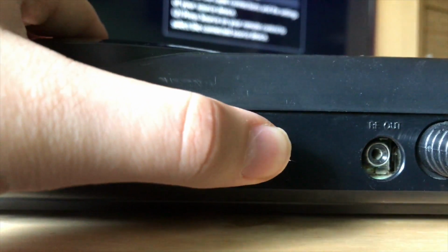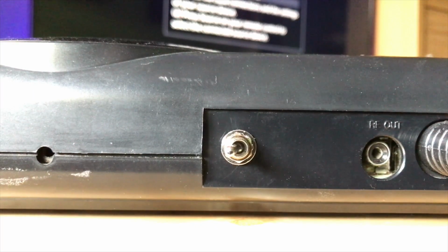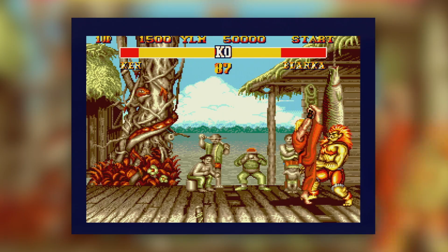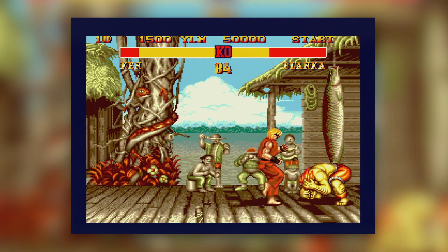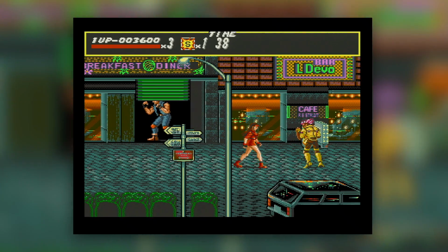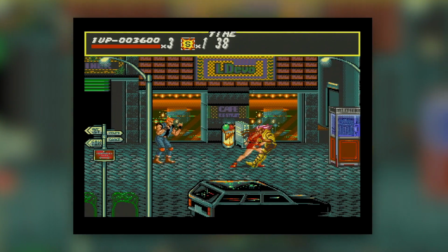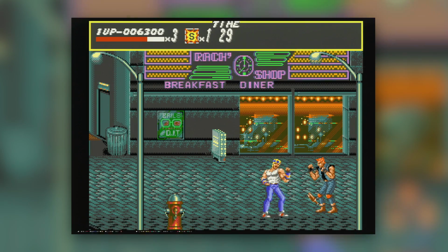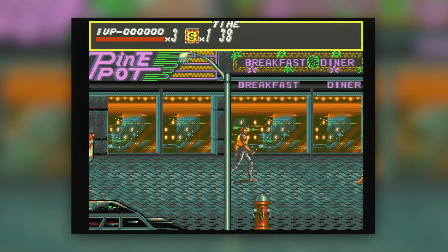However, for a quick DIY job you can mod your Mega Drive with a physical switch. The more common method is to add two switches, one to change region, the other to switch between 50Hz and 60Hz speed. But the mod I'm going to show you involves just one switch to go between the European region at 50Hz, North American region at 60Hz and Japanese region at 60Hz.